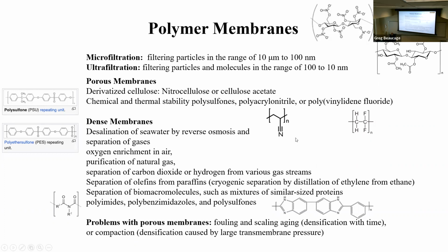And then there are fluorinated polymers that are used for membranes too. And then there are some specialty things like these aromatic polymers that have higher strength and thermal stability, right? So anyway, there are a lot of categorizations of things. If you're doing gas separation, it's called a dense membrane. It's got no pores in it except molecular scale pores, right? And this is going to do something like separating ethane from ethylene, so that you avoid cryogenic separation for the gases from the oil well.